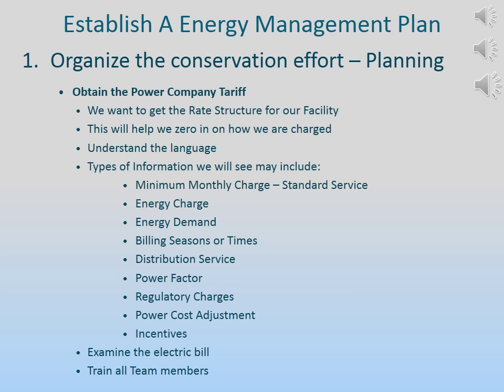It just so happens on this schedule they are the same at $5.89 per kilowatt demand and about 5 cents per kilowatt hour for energy consumption for both winter and summer. We also have distribution charges. Again, what is it telling us? It is all kilowatts. This is not a tiered system.